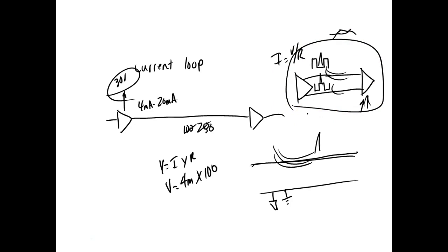These guys are not grounded. How do we get current flow? Well, the signals are always 180 degrees out of phase, yeah. So if this was an analog signal and I was sending it on one, on the other one I would be sending the inverse. So we can send analog on differential input signals, and we can use digital on differential signals.